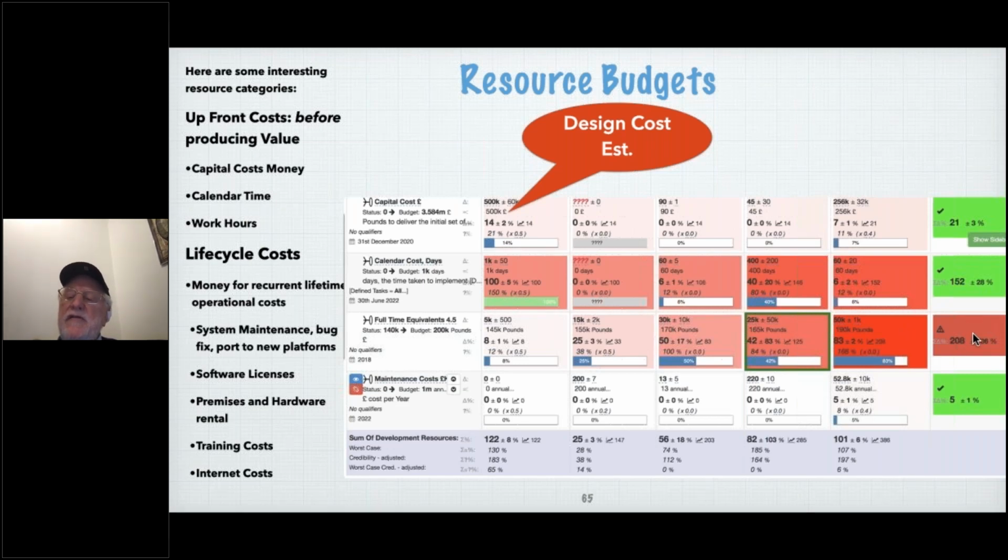Now, notice that this turned red here, and it says 208. And this didn't turn red, it's 152. The reason is we've set as a default the safety factor level at 200, or factor 2. It's quite normal in design engineering to have a safety factor of about 2, and I found that managers quite like that safety factor for both values and costs, but you can have a higher safety factor.